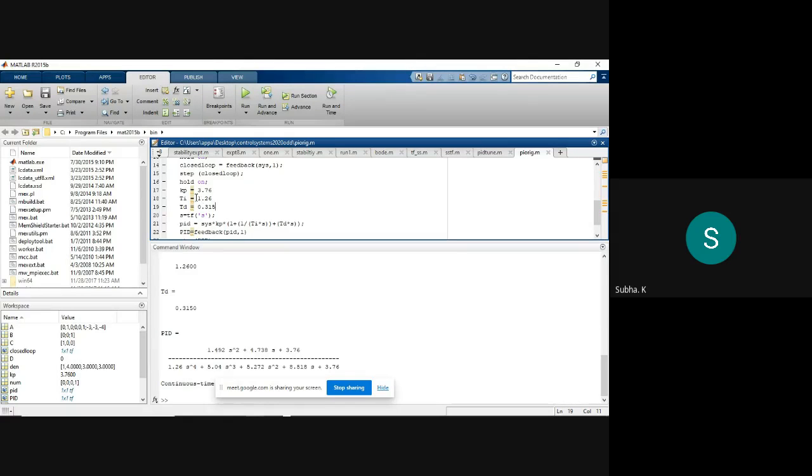So out of these 3, which is responsible for reducing the oscillation, which will make the system more stable? Ma'am, I changed TD to 1.315. No, slow and slow only you can change. Simply you cannot jump to 1.3. It will not be good. I have told you the salient features of the 3 controller terms, which is making it more stable. Let me check out with the KP. If I give 4, run again.